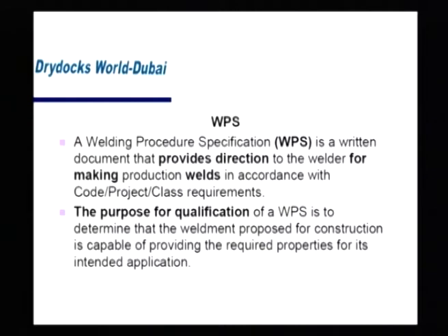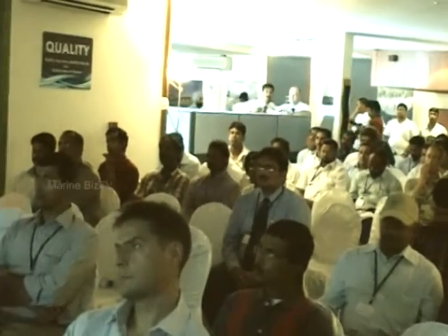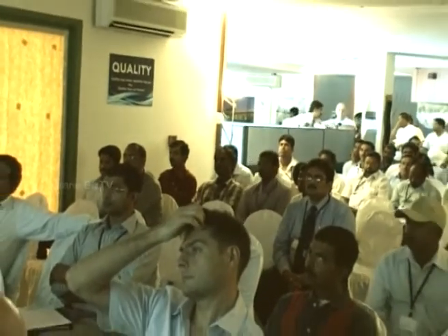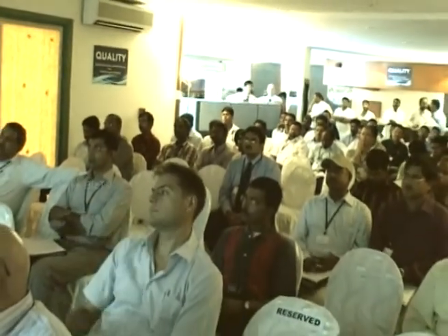So after this, the very logical question is why we are doing the qualification of the procedure. And I would say that the reason is to verify that the application of the weld is appropriate, so that the mechanical properties of the weld are appropriate. On the job, we can do NDT, of course, and verify that we don't have any slag inclusions or any other defect, but with NDT, we cannot see how much the strength of the weld is, for example.